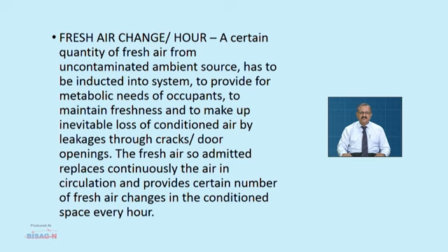Fresh air change per hour. A certain quantity of fresh air from the uncontaminated ambient source has to be inducted into the system to provide for metabolic needs of occupants, to maintain freshness and to make up inevitable loss of conditioned air by leakage through cracks and doors opening. The fresh air so admitted replaces continuously the air in circulation and provides certain number of fresh air changes in the conditioned space every hour.